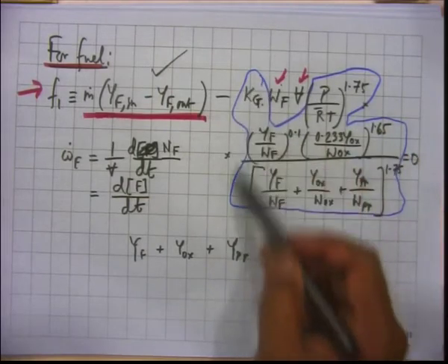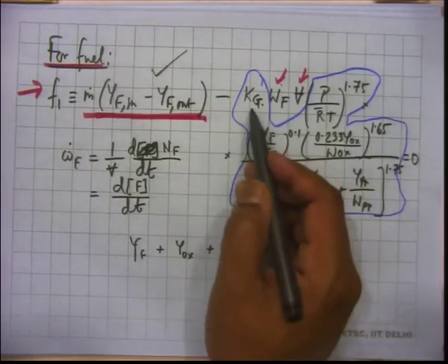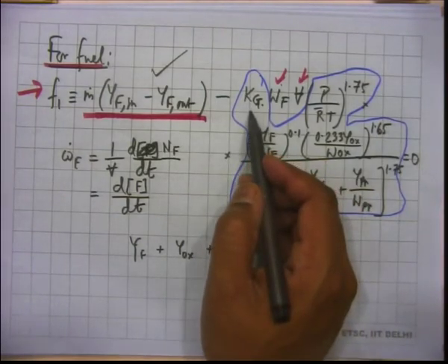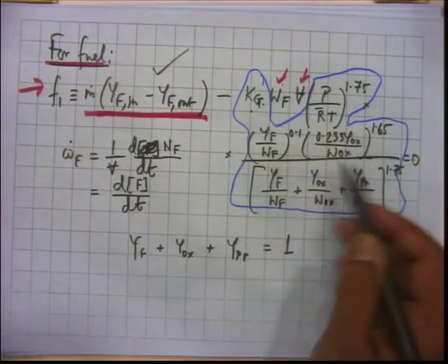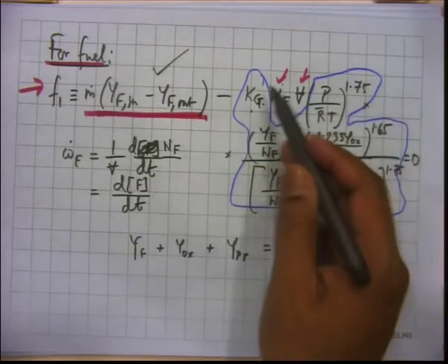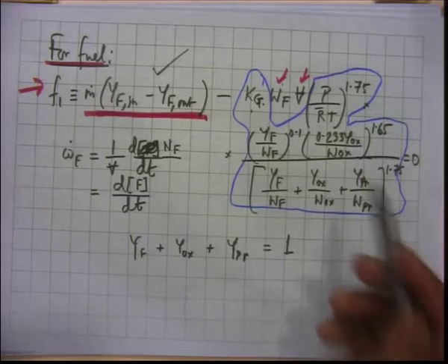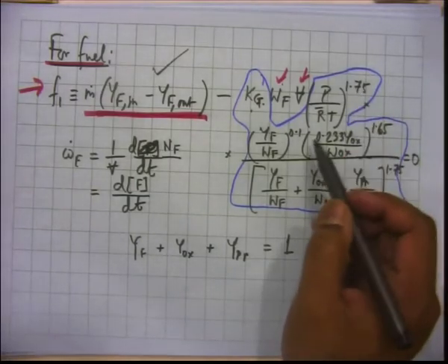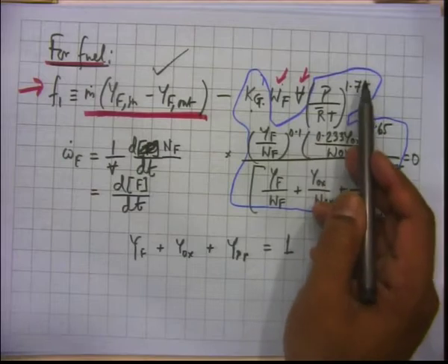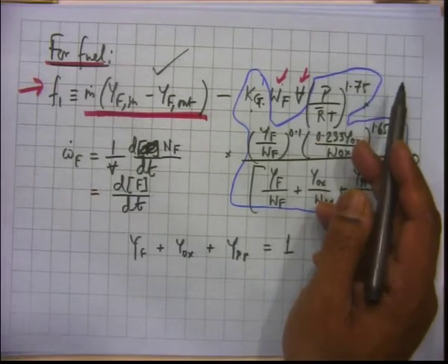So, the difficulty was here. Now, of course, we understand that there has to be a kg, because kg into concentrations raised to some powers multiplied, that is what will give this term. Now, do we understand this 1.75 now? Power 1.75 must be m plus n. Okay.